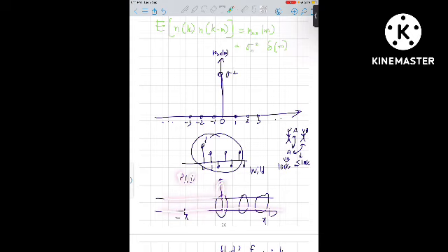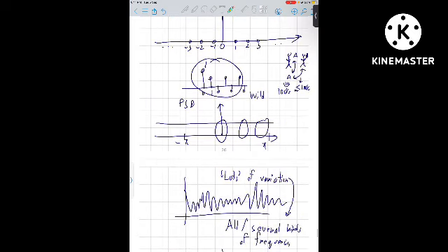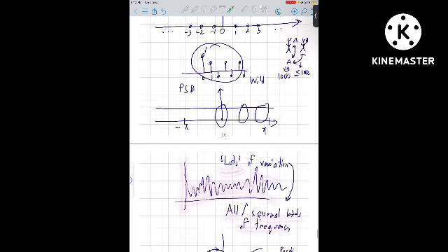So when you see the AWGN, which is the wildest of all possible signals, and you see the PSD, it has uniform power spectral density, which means it has equal amounts of low frequency components, equal amounts of medium frequency, equal amounts of high frequency components. So it has contributions from all kinds of variations.